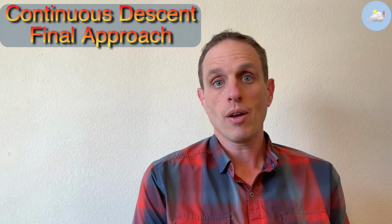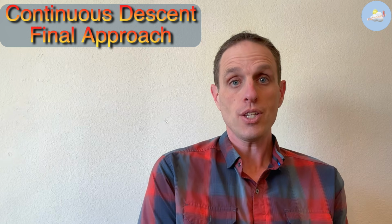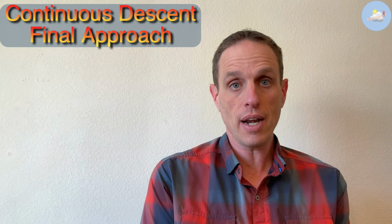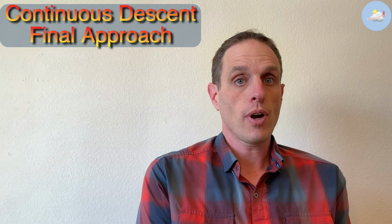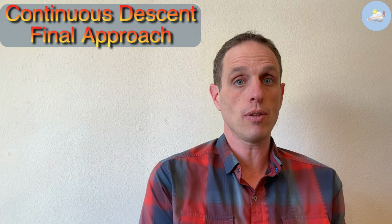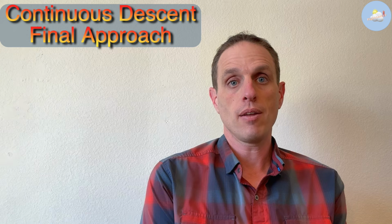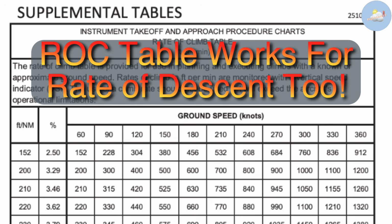Now, you might be saying, well, Joe, I fly an old airplane with old avionics. How am I supposed to do continuous descent final approach? Well, actually, you can do it there too. You don't need any fancy GPS-ness. All you need to do is figure out what angle you need to descend at between your final approach fix and the runway. And basically, based on your ground speed, you can figure out what rate of descent you need to descend at.